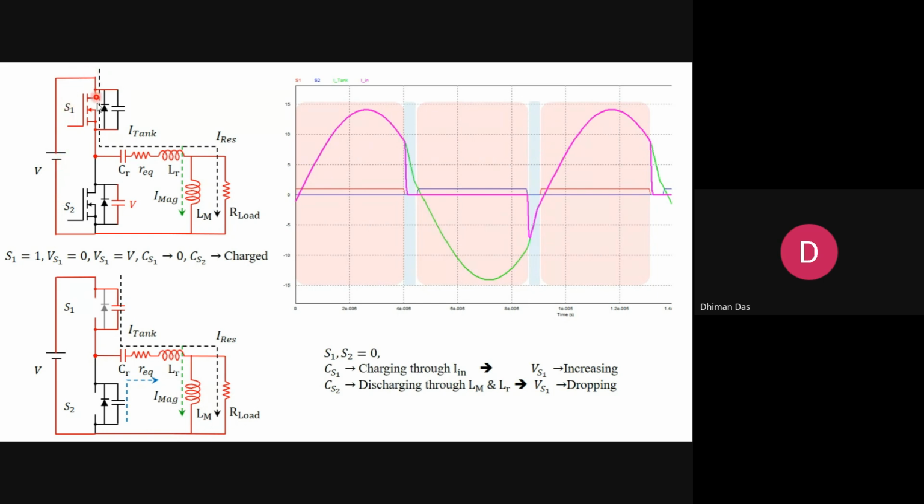That source is connected to this half bridge, and the middle of the half bridge is either 0 or 1. So when the top switch S1 is turned on, this node is connected to the positive supply, then the voltage across this node with respect to the ground is plus. Now when the top switch is off and S2 is on, then the potential at this node is 0.